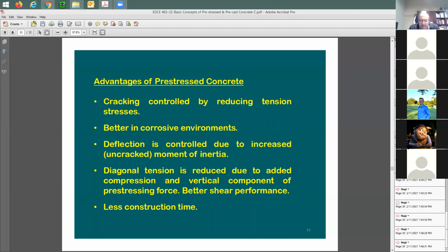Let's say that 3 inches is too much and you cannot satisfy the code requirements. But in pre-stressed concrete, you can camber the beam, let's say at least 1.5 inches. So once you pour the concrete beam, it's going to go up 1.5 inches. Now you put all the dead load on, it's going to bring it down 2 inches, but it already went up 1.5 inches in camber. So deflection due to dead load effectively becomes only 0.5 inch. Then you have an additional 1 inch for the live load deflection. So total deflection at the end of the day in pre-stress is going to be 1.5 inches.